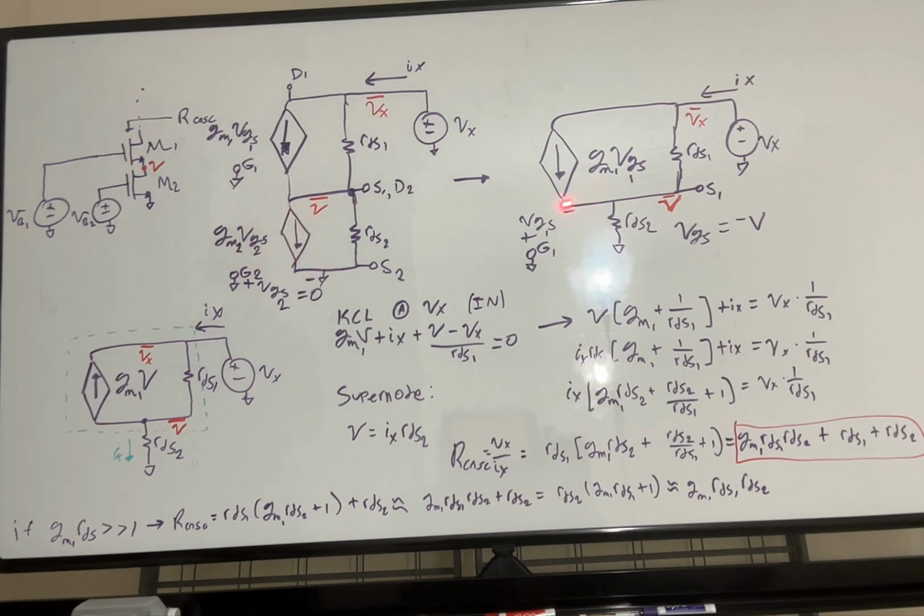So we'll draw the circuit again over here. Now we can look over here. And we'll notice that this current source is gone. That's why I didn't draw it, because it's drawing 0 current, so it's an open circuit. And we've still annotated VGS1, which is gate minus here. Now we'll notice that I annotated this node as V, right? I've just called it V because there's only 2 nodes in the circuit. There's the test voltage node with the test current coming out of it, and there's the voltage node. And since VGS starts at VG, it's really just minus V.